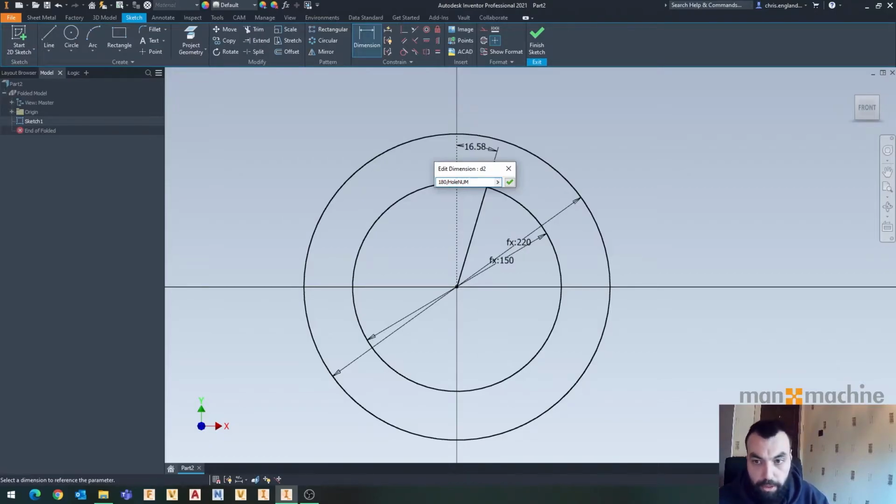Right? Whole num. Now, as I mentioned, if ever you do forget a parameter, you can always just click on your little arrow at the end of any parameter field that you're trying to input and just click list parameters, and you can find a list of all your custom named parameters. So if ever you forget one that you typed, or perhaps you made a typo and can't get it right yourself, you can always just go and click that arrow and find it there.